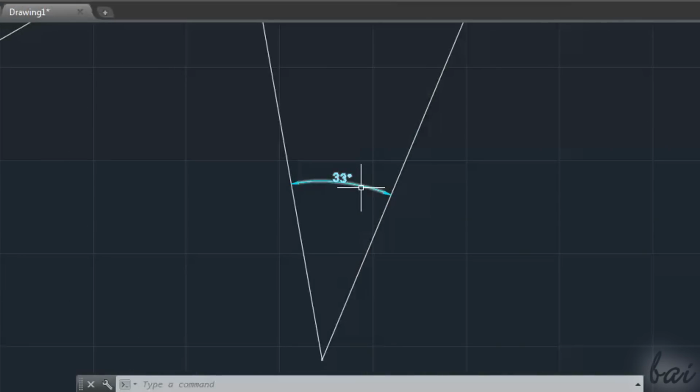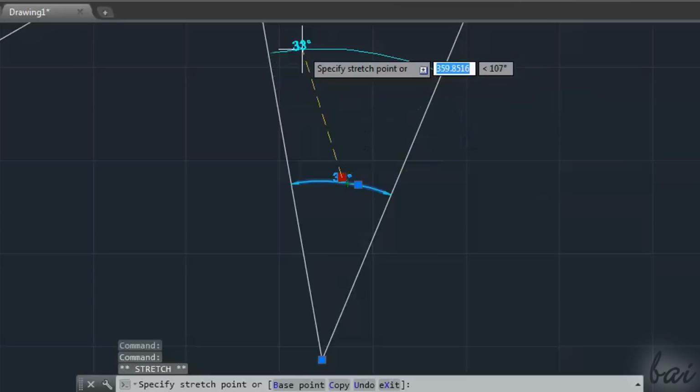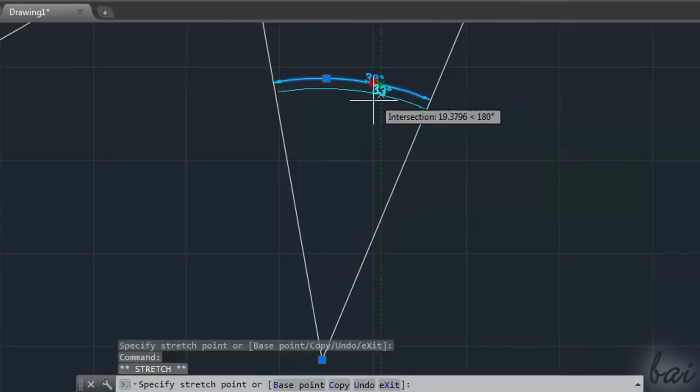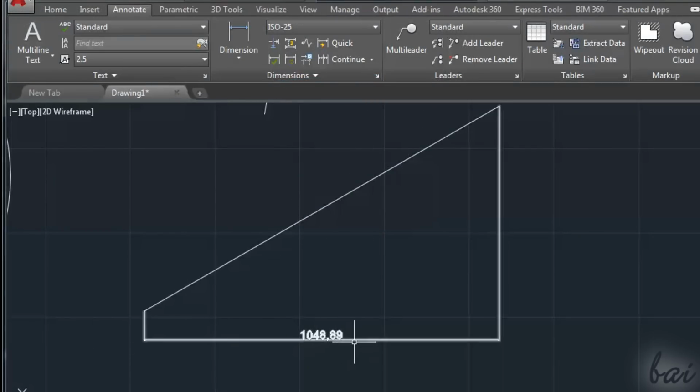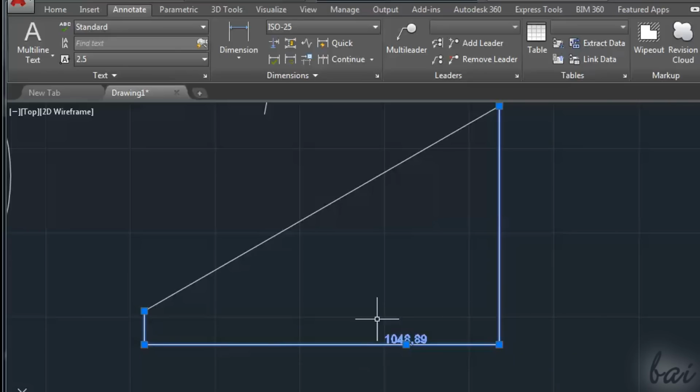Mind that the annotation is a known object that you can move, edit, and delete as a normal object. When you select it, additional blue nodes appear. These do represent where you are taking the measurement. Changing their position may change also the measured value.